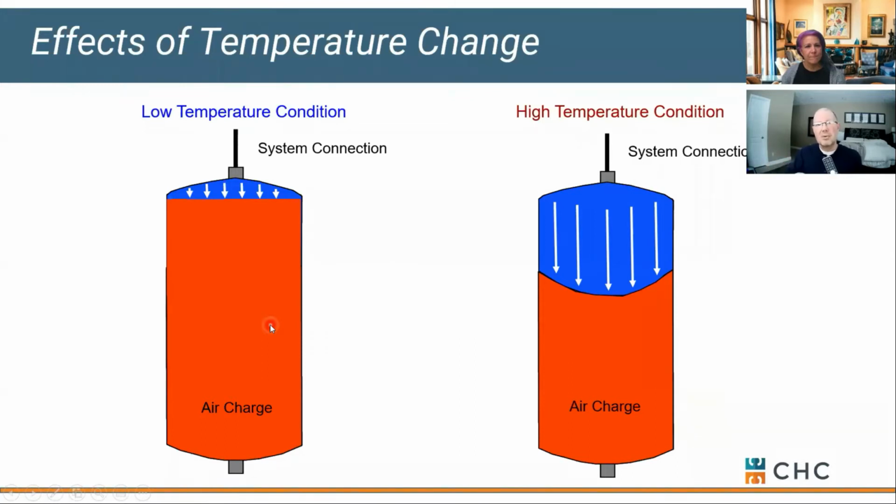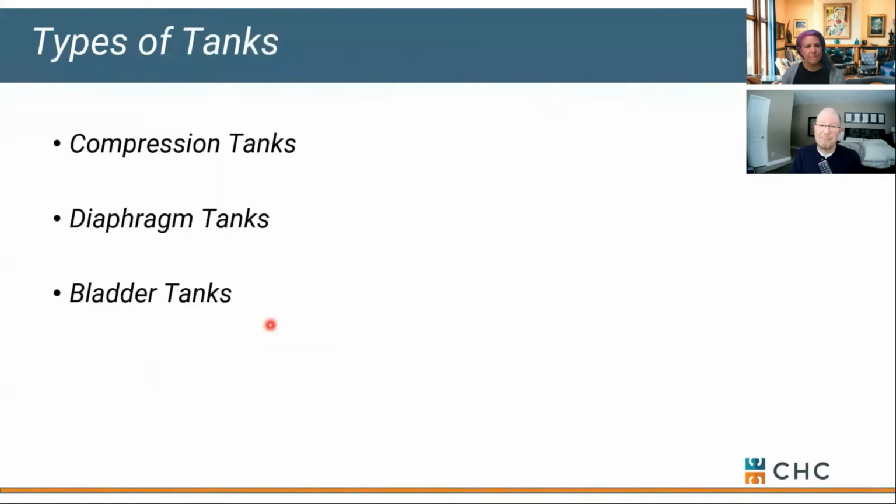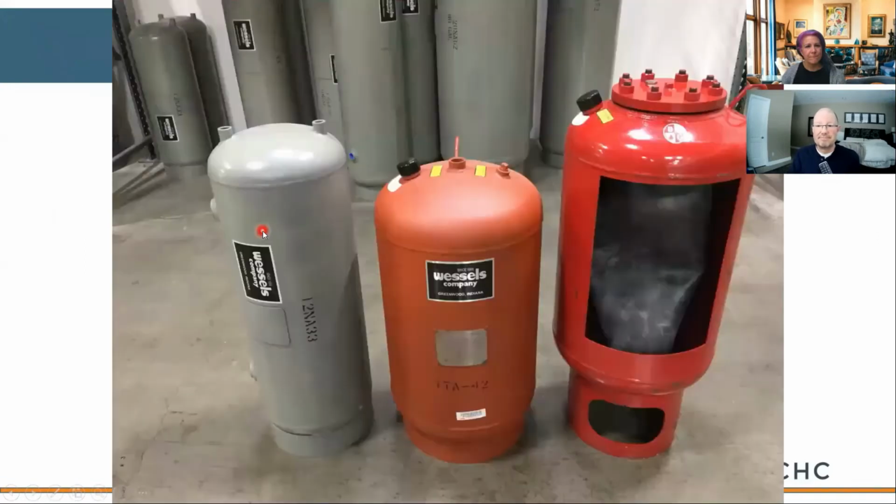Let them expand and contract as we heat and cool water. That's it. It couldn't get any easier than that. Now, there's three styles of tanks. Old school would be a compression tank. More modern would be a diaphragm or bladder style.